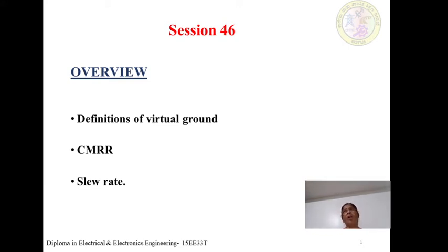What components does it involve? It can be defined in 3 stages. The first stage is a differential amplifier, second, followed by a high voltage, high gain common emitter (CE) amplifier, and followed by the output stage. As we know, the common emitter configuration amplifier we have already studied in the 5th unit. In detail, the first stage of the operational amplifier is the differential amplifier.